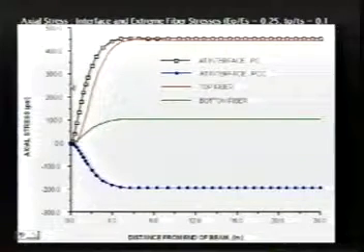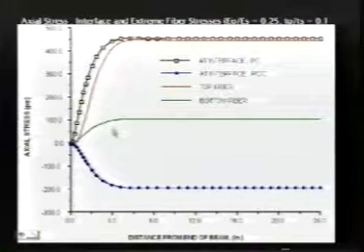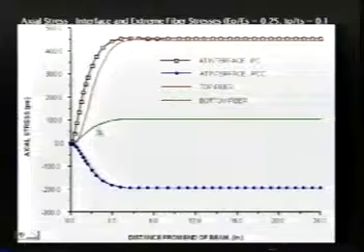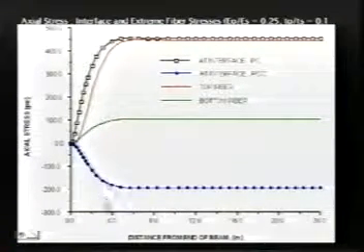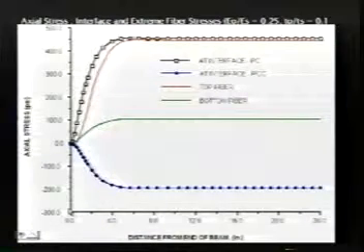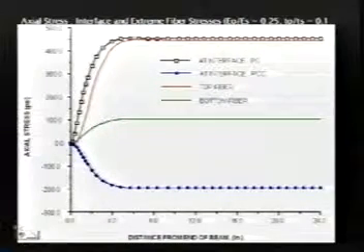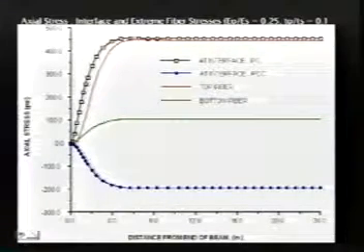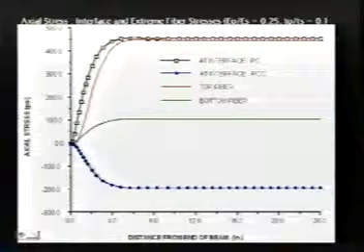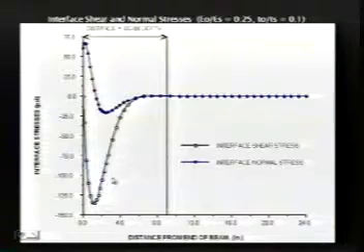This simply shows you that if you look at the stresses in a beam that has an overlay, these stresses tend to occur fairly near the edge or the boundary. That boundary could be the edge of an overlay, the edge of a slab. It could be if you had a crack that goes all the way through the overlay and the slab. That could be the condition. Let me go on to the next slide.